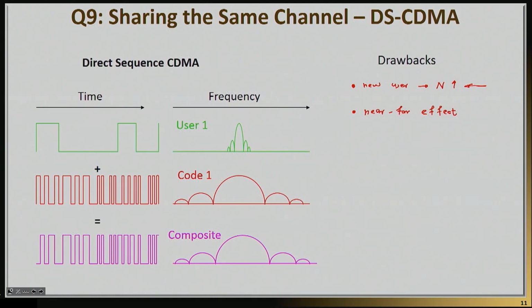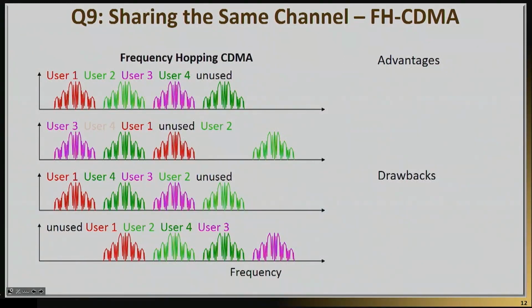And in fact, we do deal with that on an everyday basis. Many 3G systems today are actually using CDMA techniques. And the way they do that is that constantly the base station listens to how loudly you speak and sends you back a note that says, hey, tone down, you're too close to me. Or you can actually transmit a little bit higher, I can't hear you well. But there is this constant feedback all the time that must happen to basically keep the near-far effect under control.